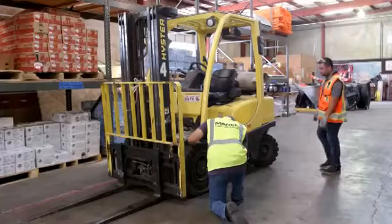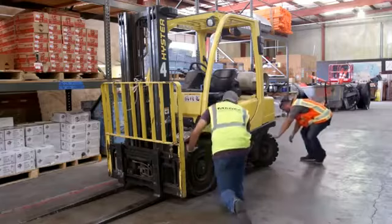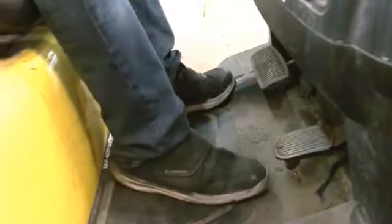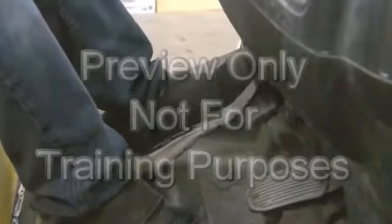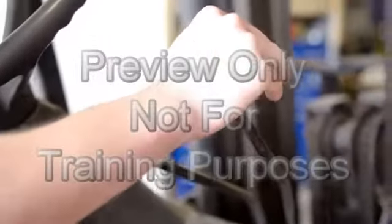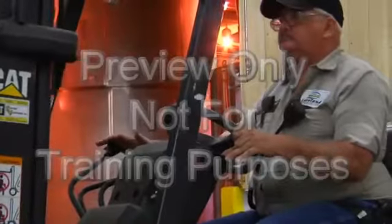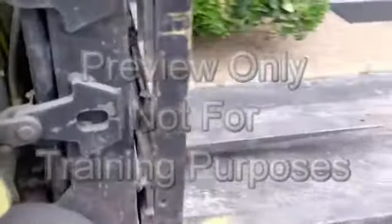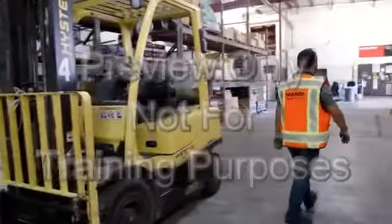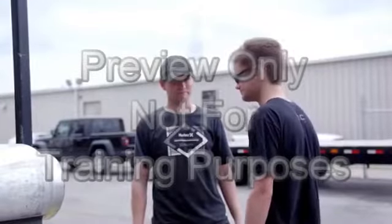Operational inspection. After completing the pre-operational inspection, operators should conduct an operational inspection with the engine running. This inspection includes accelerator linkage, inch control if equipped, brakes, steering, drive control, front and back, tilt control, forward and back, hoist and lowering control, attachment control, horn, backup alarm, hour meter. If you find anything wrong while doing either inspection, write it down on the inspection sheet and report it to your supervisor. Never drive a truck with problems.